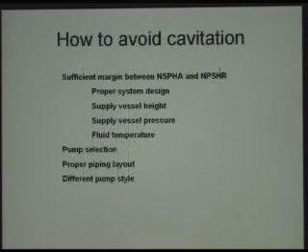You said this happens because of the mechanical impact of the bubble? It's the pressure over area as this vapor bubble collapses, and at the moment that it collapses back into a liquid, it imparts a relatively small force, but it's over an extremely small area, so the stress is extremely high. And the Hertzian contact stress levels are what define if we're going to have material erosion or not. And so if you exceed those stress levels, then you start to have pitting effects on the metal.